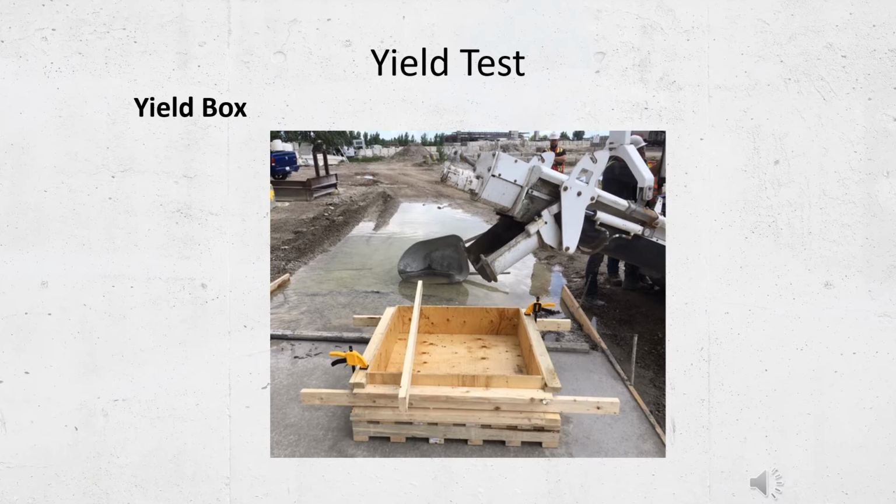However, we're going to need to run within batch uniformity testing, as well as securing concrete test cylinders for compressive strength testing and hardened air void analysis. So we might as well select a mix that we can use to cover all elements of the certification process. To that end, we're going to want to select a mix to produce a CSA Class C2 exposure mix with a design strength of 32 MPa at 28 days, air entrained 5 to 8% with a target slump in the order of 80 to 100 millimeters, plus or minus 30 millimeters.